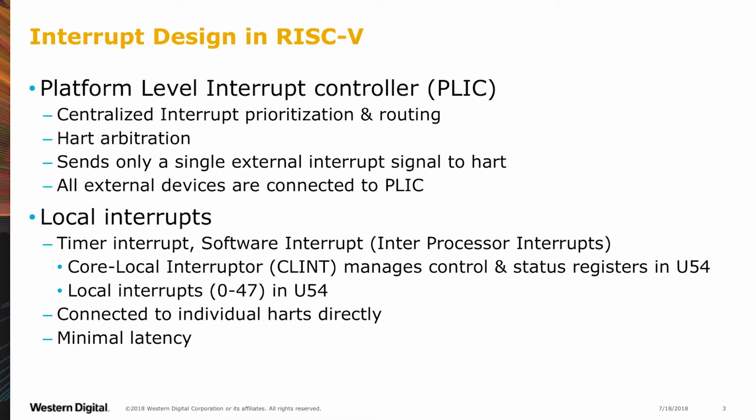And we have local interrupts, which include the timer interrupt, the software interrupt, and the local external interrupts, which are CPU interrupts. Since I'm talking only in terms of Linux support, how it's designed and implemented in Linux, I'm going to talk about how the U54 core from SiFive, which is the only core that has Linux support, manages it and implements it, and then how we manage it in Linux.